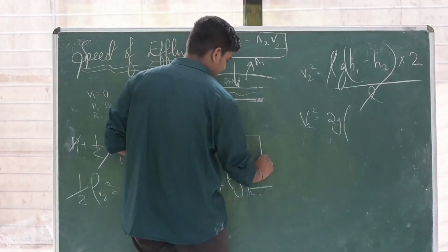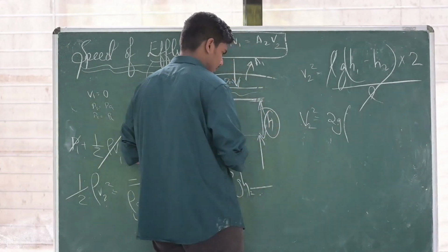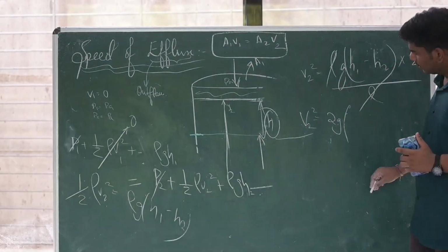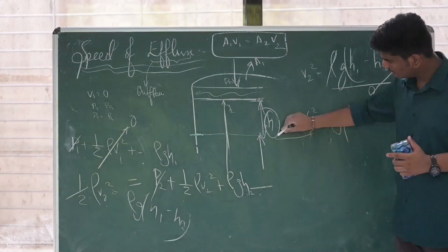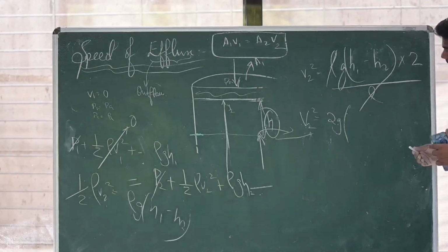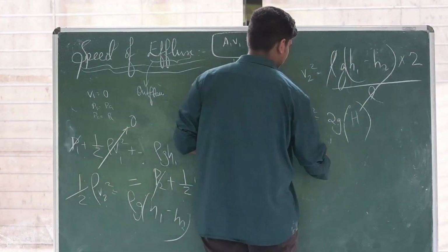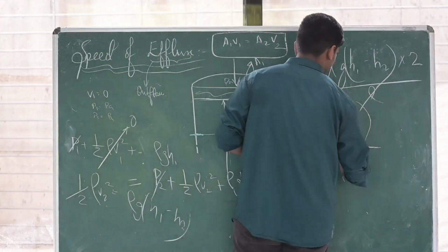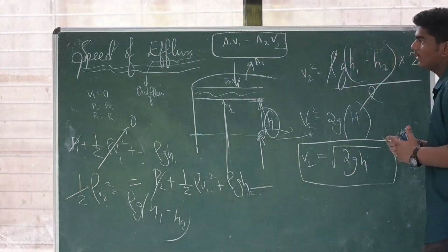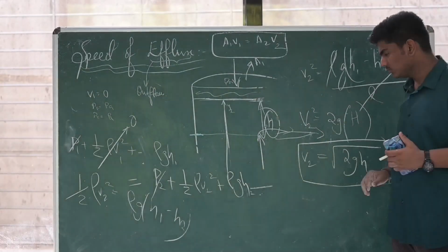This height minus fluid height till here will give you H, capital H, which is till where the fluid will flow, and after this point the hole will fall above the fluid. So fluid can't generally beat gravity and come out. So capital H. Now V2 is equal to root 2GH. So we have found the speed of the outflow from this hole here, which is root 2GH.